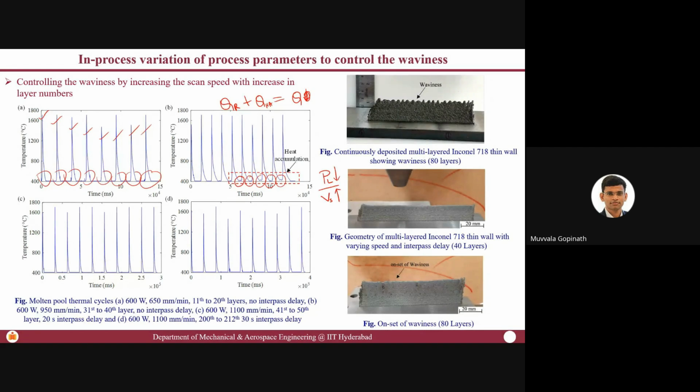So this way, if you can manipulate these input parameters, from a deposition like this, where you can see there is a lot of waviness, which is not acceptable, you can come to a deposition like this, where you will not see any waviness. Hardly have we looked into four slides, but there are a lot of systems and sensors integrated into the process such that we were able to generate this kind of data and these finished uniform balls.